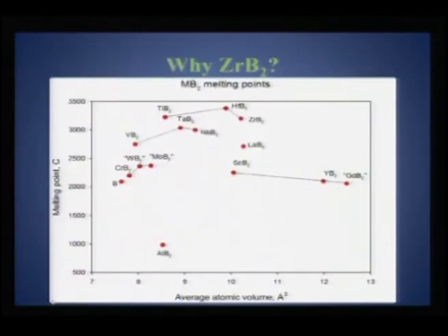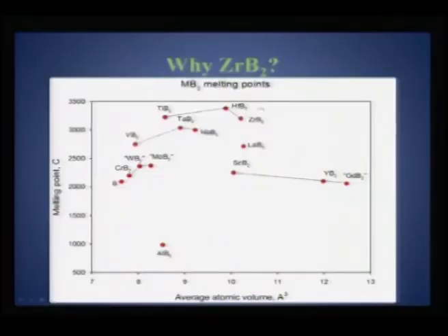So this is typically the level at which you need to start in order to get 2 gram quantity of gallium nitride. Main issue as far as gallium nitride growth is concerned is the container in which you are growing, because it should not diffuse or react with your melt, and in that case usually borides are used. So in any flux growth method, all that you should remember is that metal borides are the most important ones to be used.